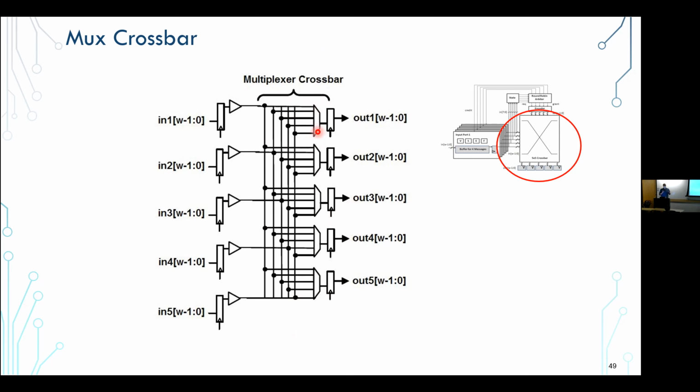So it's a much nicer thing for the tools to work with to achieve the density, because they can determine the area for the wire routes and repeaters, and then they have a whole other section for logic. And that section is localized per port. That's what's important, right? Because then you can locally optimize that logic without having to have it be distributed like in a tri-state fashion.